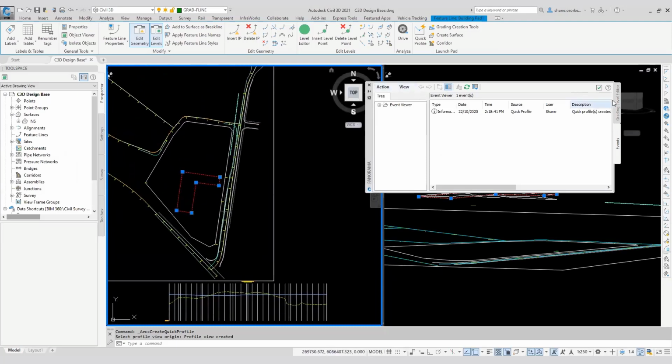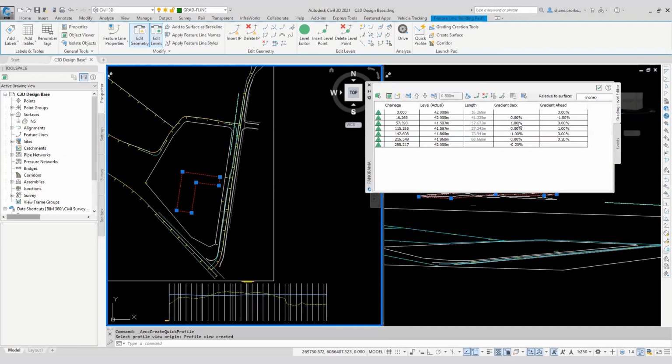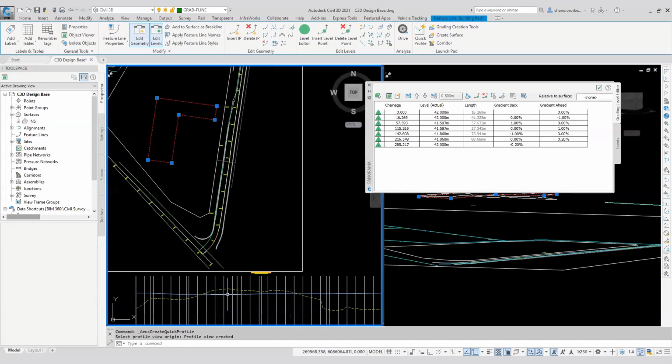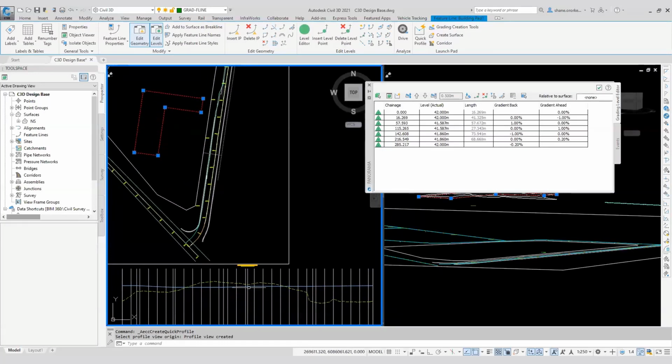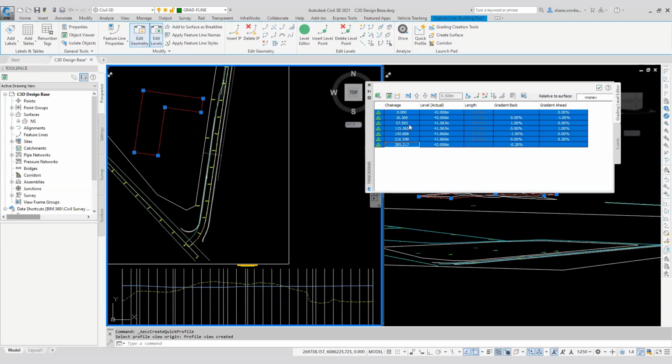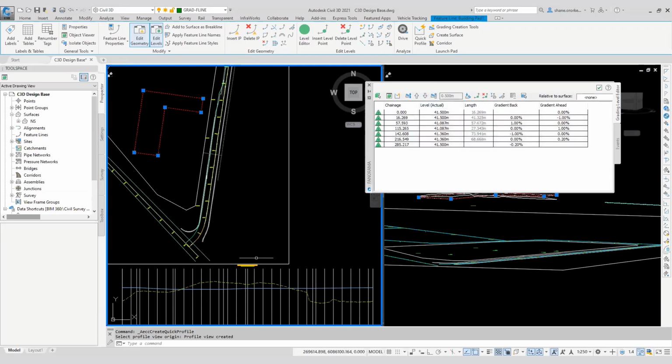And again, if I go back to the elevation editor, if I put something dramatic in here like minus 10%, I can see it happen there, and I can see it certainly in 3D. The other things you can do with this, I mean, if you thought this building pad was a bit high, just by looking at this, you might want to raise and lower it. So you can highlight cells in here, and there's a raise lower tool. Okay, so I could just hit the down arrow here, and I drop the whole thing by half a meter, right?